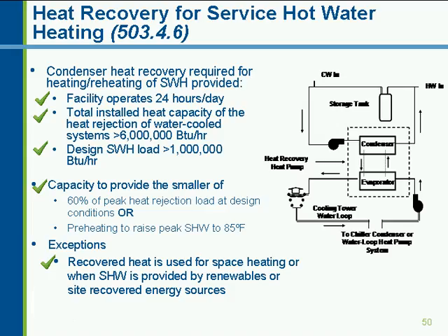Okay, how does the condenser heat recovery for service hot water save energy? So we look at the schematic for that condenser heat recovery. And this applies if a facility has a water-cooled chiller with a large cooling load as well as a large service hot water load, and the facility operates 24 hours a day.